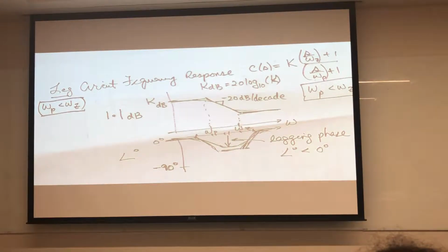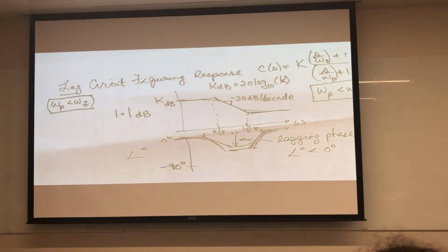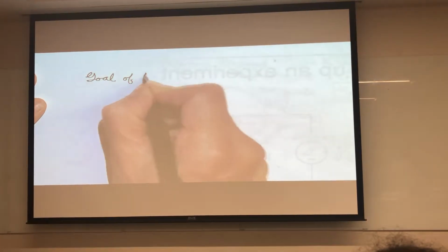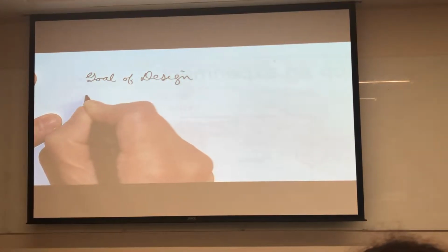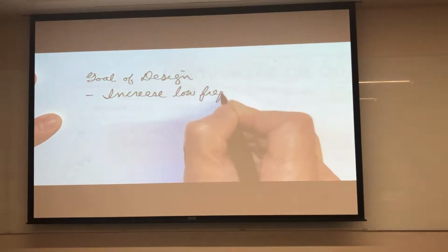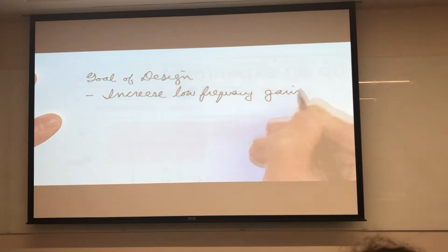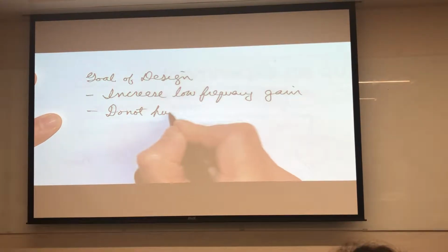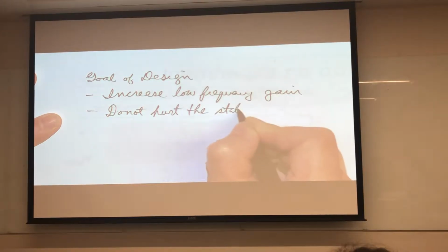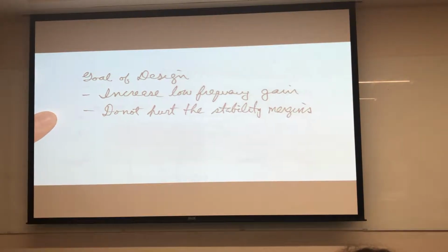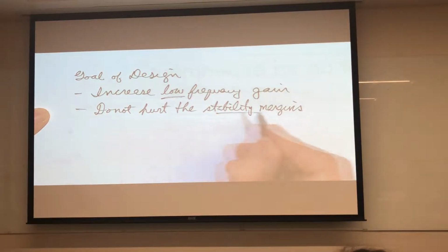And so the key idea with phase lag compensation is that we want to increase the low frequency gain, but do not hurt the stability margins. Okay, increase the low frequency gain, but do not hurt the stability margins.